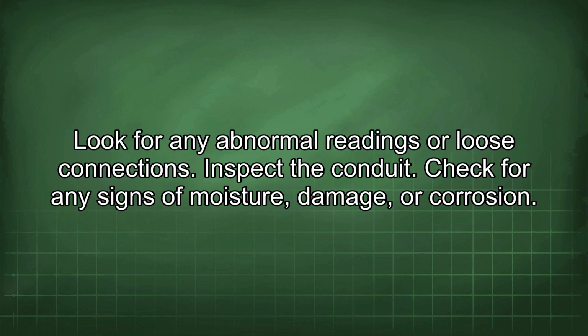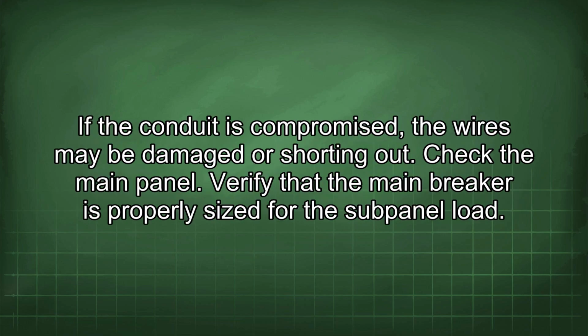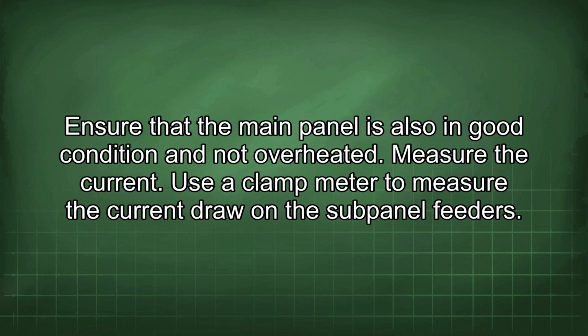Inspect the conduit. Check for any signs of moisture, damage, or corrosion. If the conduit is compromised, the wires may be damaged or shorting out. Check the main panel. Verify that the main breaker is properly sized for the subpanel load. Ensure that the main panel is also in good condition and not overheated.